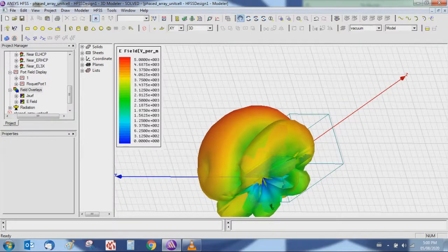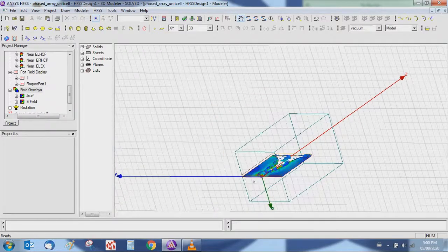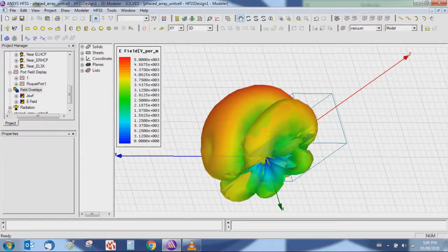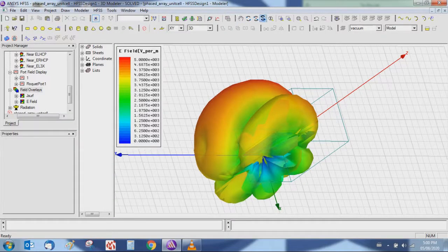Phased array antennas can be optimized for performance at the element, subarray or complete array level based on element match, passive or driven, far field and near field pattern behavior over any scan condition of interest.